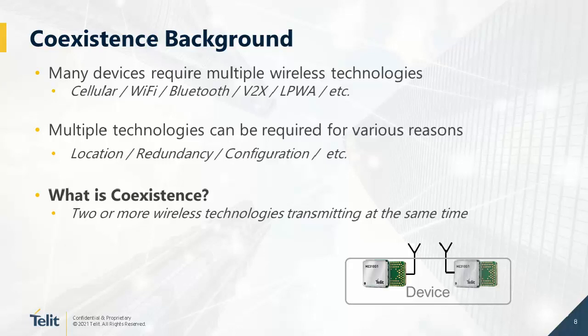We're also seeing multiple technologies used for gateways, right? So as Steve was mentioning, to pull out the data. So you may have endpoints that are communicating on a more local area technology, whether it's Wi-Fi, Z-Wave, Zigbee, proprietary, and then pulling that data into a gateway and then spitting it out over cellular or Wi-Fi over to the internet. So we are seeing a tremendous amount of unique use cases using multiple technologies.